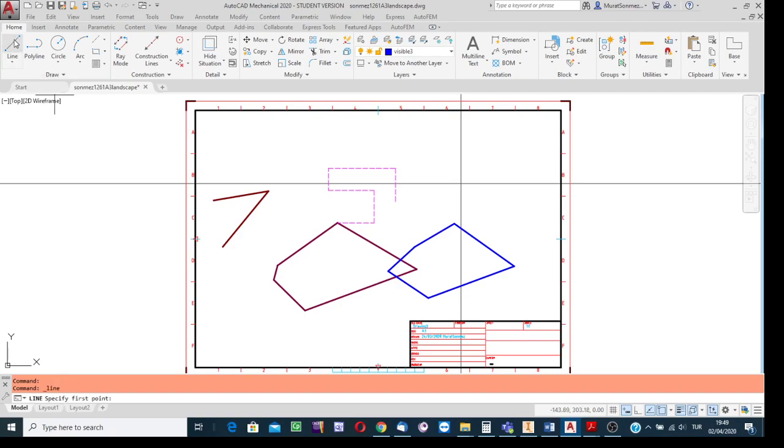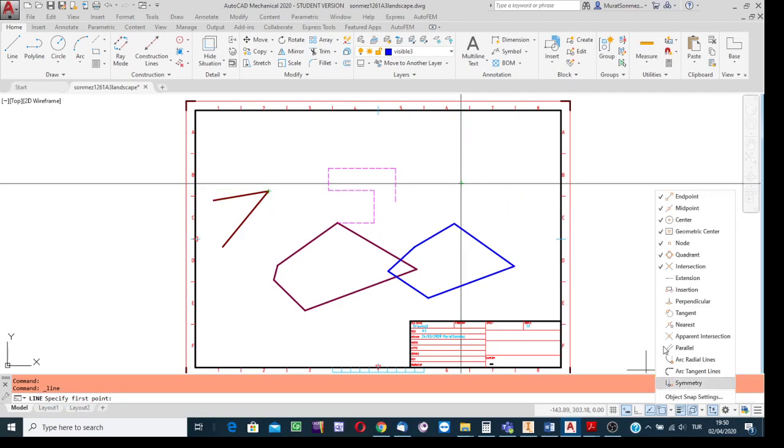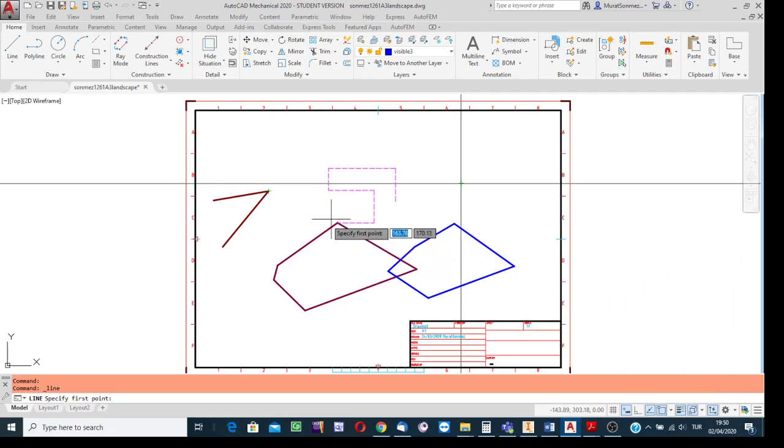Start the line creation process, and then use the snap facility. Yes, endpoint can snap the cursor, intersection can snap the cursor. So here check whether endpoints and intersection points are enabled. Yes, for both of them enabled. So indicate this highlighted point with a click as the starting point. Indicate this intersection point, which is now highlighted, with a click. That is it. Here is the line.